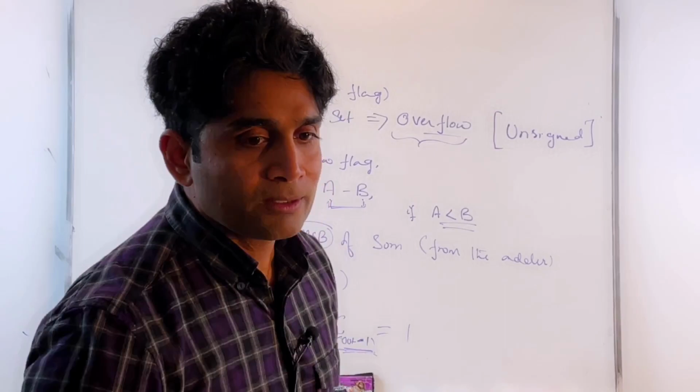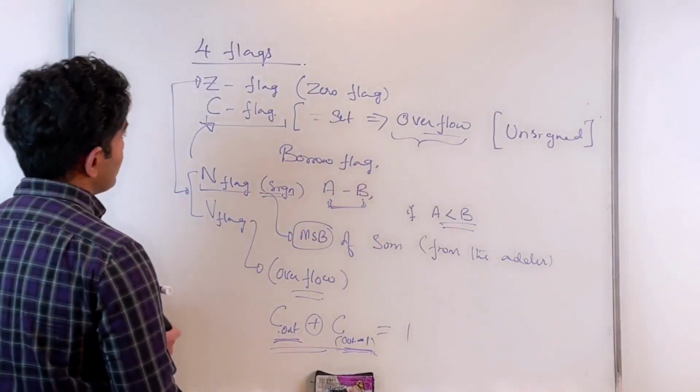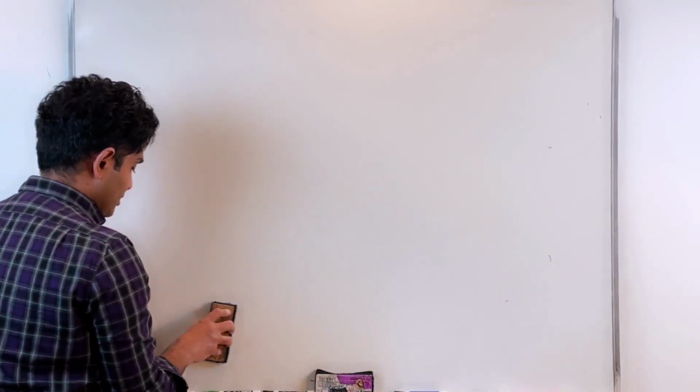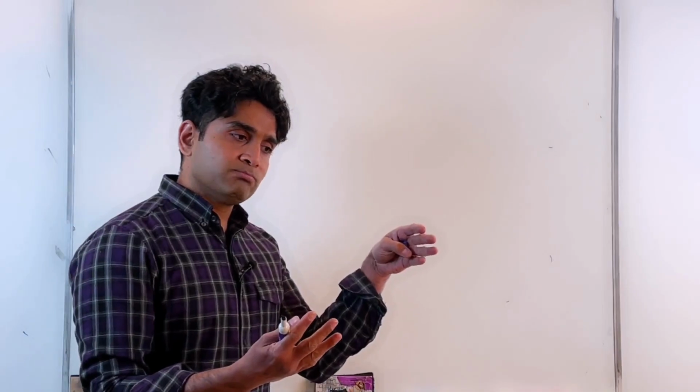So now let's go to Yusuf's question. For BCD, when we derive the BCD adder using just binary adders, I quickly realize that I should be using a 4-bit binary adder, because each decimal digit is represented as a 4-bit binary code, which is the BCD, binary coded decimal. When I'm adding two digits together, I'm adding 4 binary bits together. So why can't we, instead of designing everything at the gate level from scratch, use existing 4-bit adders? That's exactly the approach we have taken.